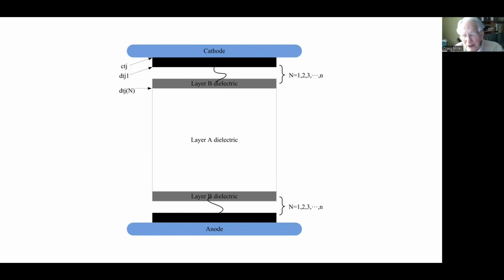It's more complicated, of course, but insulators like this have a higher hold-off voltage. It's in my paper, but I'm not showing it here. One found an optimum of about 3 insulator layers caused the highest hold-off, a significant increase, and then it decreased again.